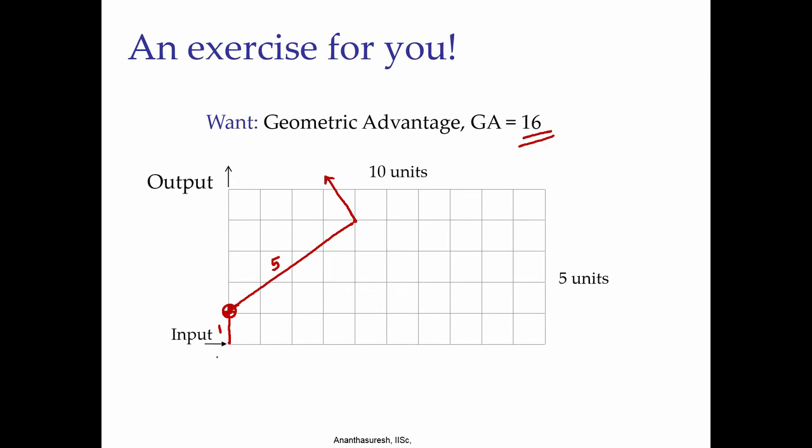If this moves by, let us call this displacement x, which is in that direction, this will be 5x because this is the instant center. So, now if I extend this further, I get another instant center. Let us do that in a different color. So, I have another one here, that is our instant center, and this angle here is tan inverse 3 by 4.